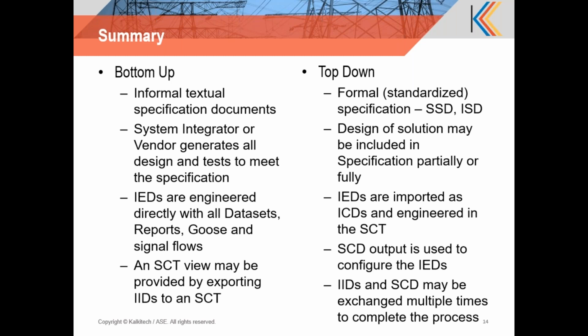But to send a bigger value, it uses 2 bytes or 3 bytes or 4 bytes. So the length is variable, which optimizes the bandwidth but makes it difficult to process automatically. So now fixed offset forces all the data to a fixed offset. So all 32-bit integers will be encoded in 5 bytes, which makes it easy for automated systems like a programmable logic controller to extract the data without worrying about how long it really is.